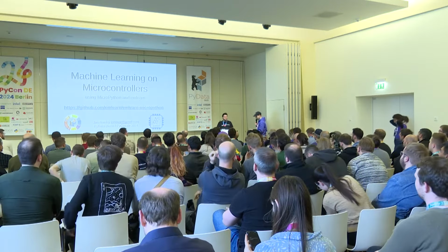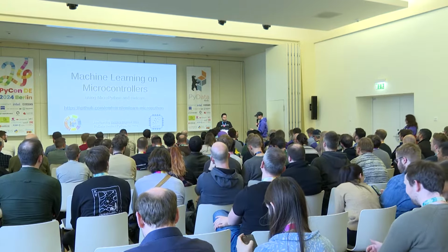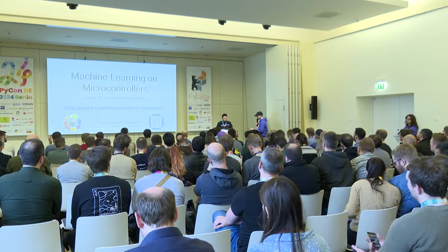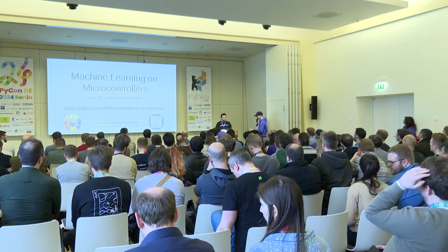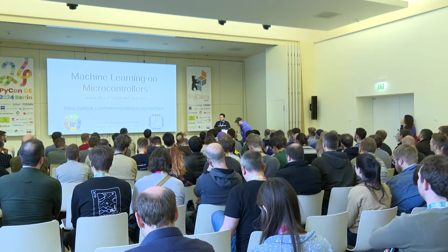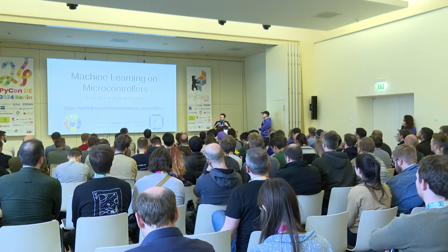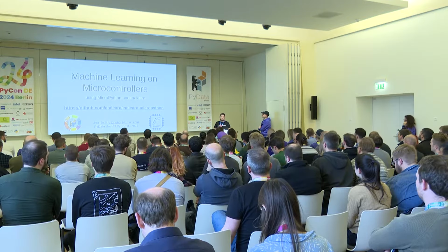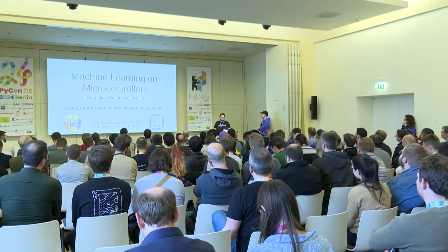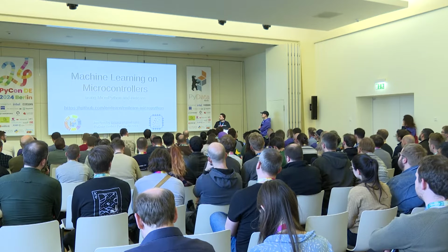All right, thank you, Jon, for your presentation. Maybe one question. Does emlearn MicroPython provide access to microcontroller hardware-specific functions, such as timer interrupts, because they are not provided with Python? Yeah, that's a great question. There's a machine module and a couple of other modules which will give you access to basically all the microcontroller-specific functionality from Python. Not necessarily everything, but the goal is to have everything accessible. On most ports, maybe 90% of the stuff is accessible from Python.